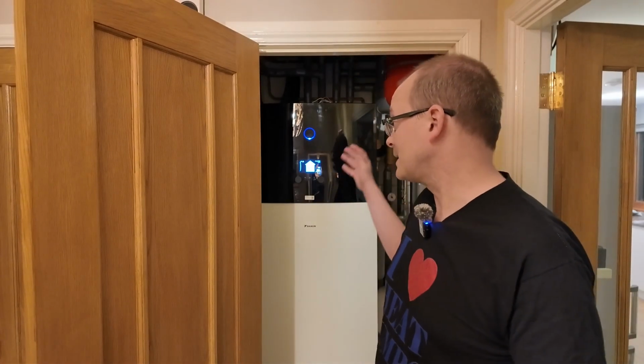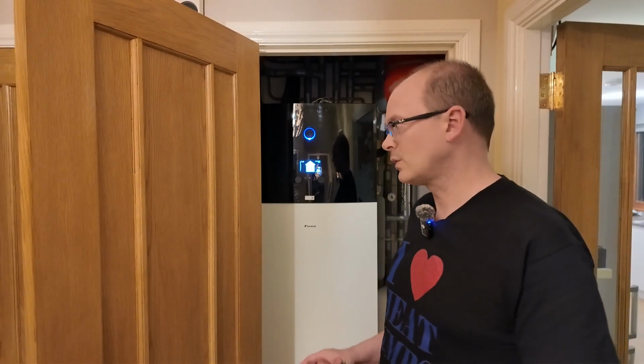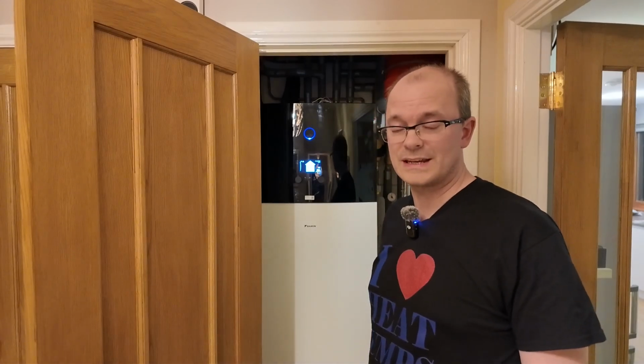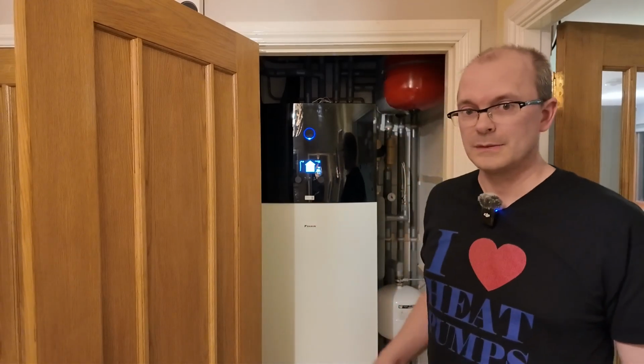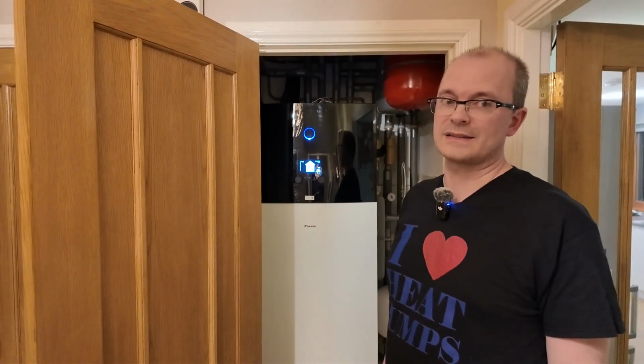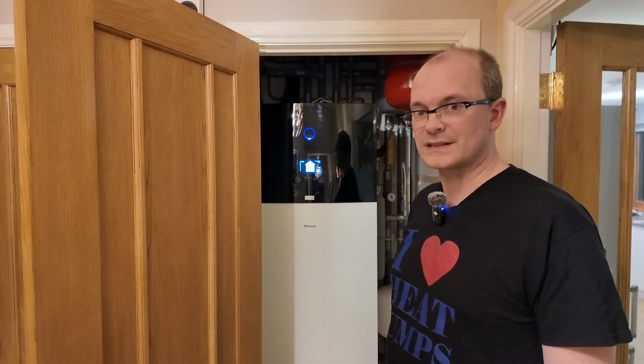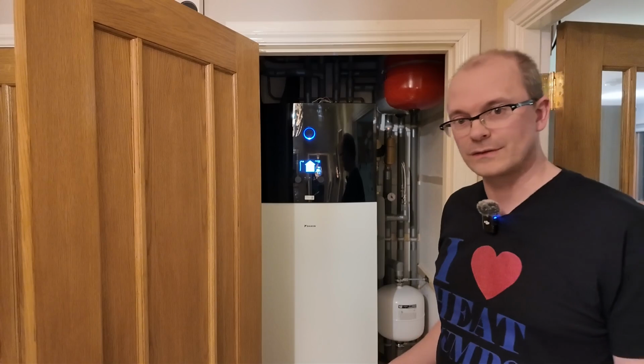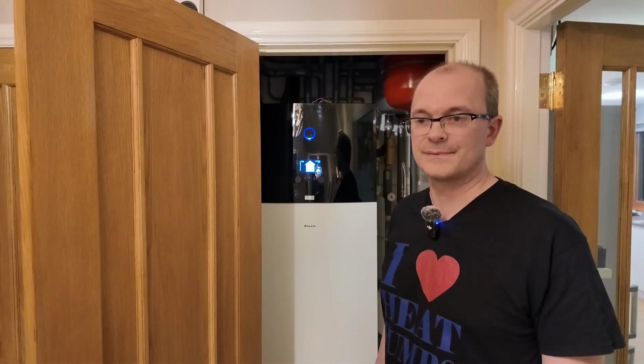Now it's fair to say that the number of times I'm interacting with the heat pump is getting less and less, and all told, this is pretty well tuned in, certainly at the milder end of the temperatures. The minimum temperature I've got as being 28 degrees Celsius for the set point water temperature, and that will happen at a temperature of 10 degrees Celsius outside.